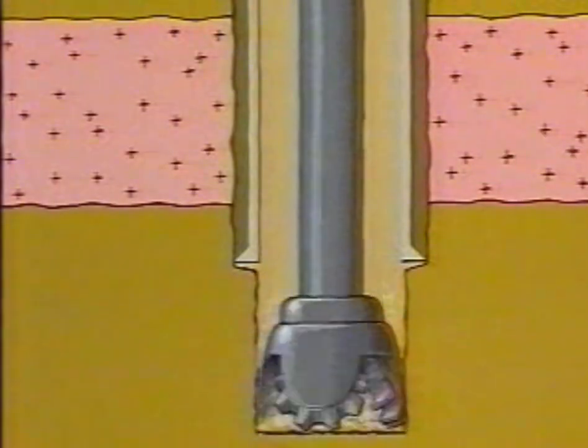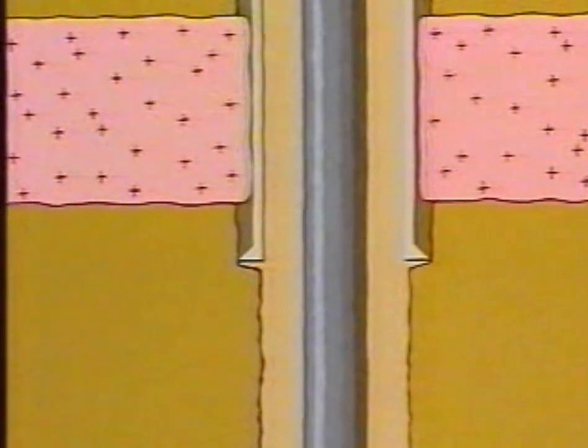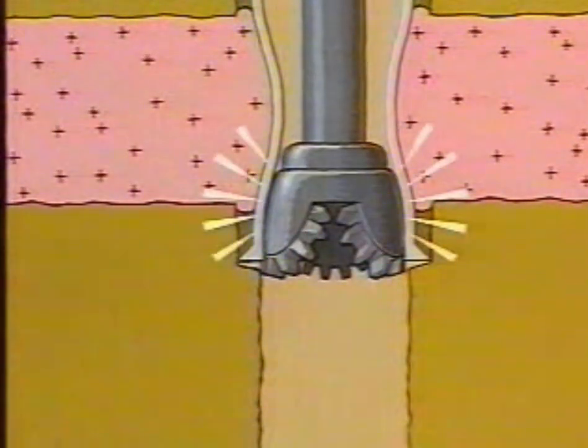When drilling with the casing in position through plastic formations, such as salt, it's possible for the forces exerted by the surrounding formation to exceed the casing collapse pressure. This can result in damage or deformity to the casing, which can jam the string or BHA, especially when tripping out. This usually occurs when the casing is too light, or when it is too old, which effectively reduces its grade. Or indeed when the casing is landed with too much tension, which reduces its collapse rating.